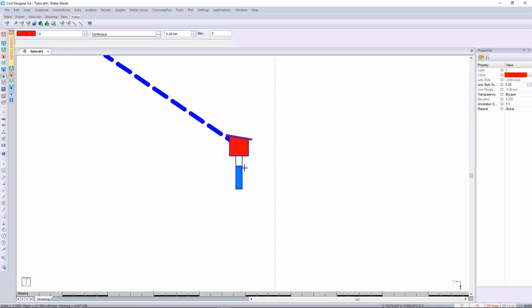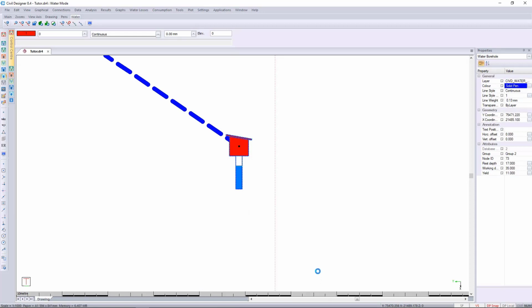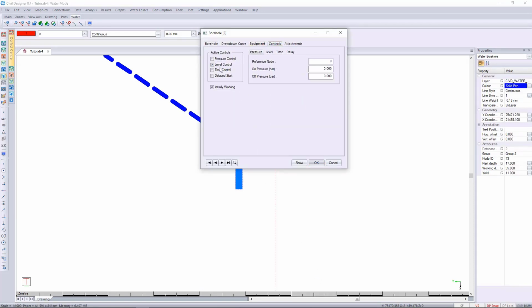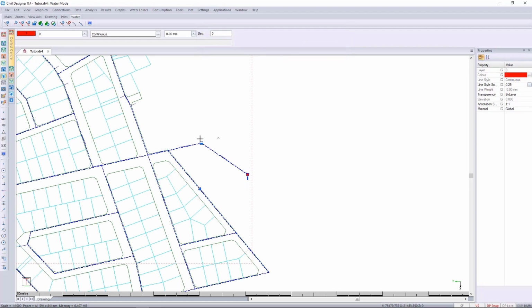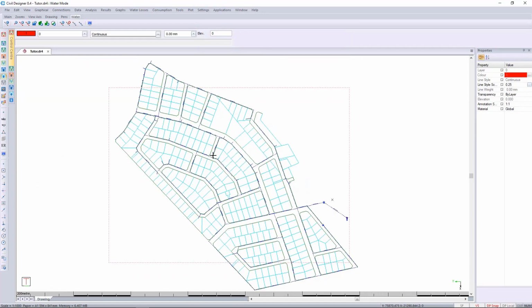One thing just to keep in mind when you go back to your level controls: if we go there now and we go to the controls, you'll see that it says level control here, but it says pressure. And you actually need to change over to the level tab. The reason for that is because we can't have radial buttons here, because we would like you still to be able to use all of these controls, not just one of the controls. So that's why we have to have ticks and not radial buttons here. So just make sure that when you're here, you don't go and say, oh no, where are my values, and repopulate. You need to move over to the level control. Cool. That's just one little catch that you need to look out for when populating those cells.